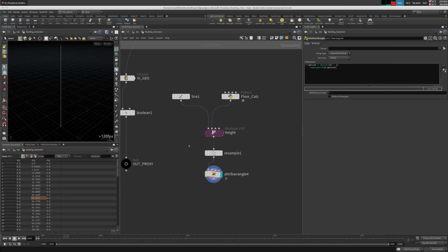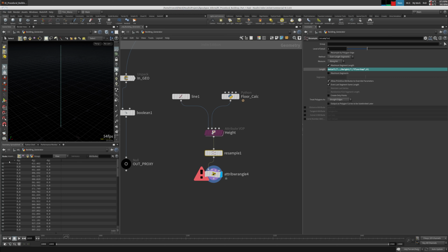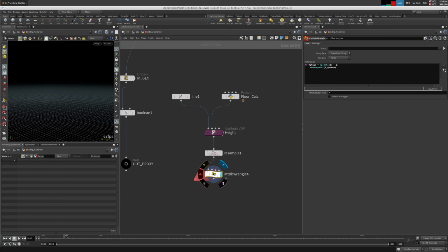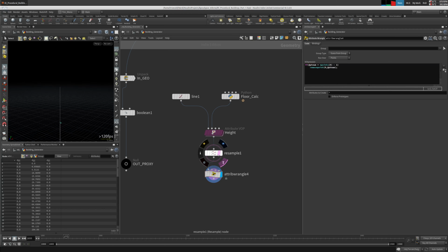N points gives us all the points, which is 83. So if I look up here, turn on the point numbers, let's do it here. The last point is 83 because point numbers start at 0, so 0 also counts. So I want to remove this last guy, which is n points. Why is it erring? Semicolon. So now it should be removing the last point. Okay, let's call it remove last point.